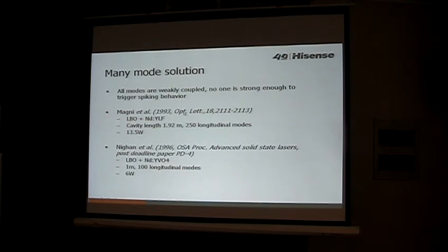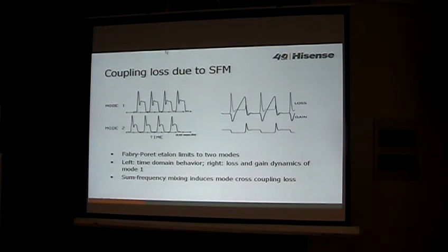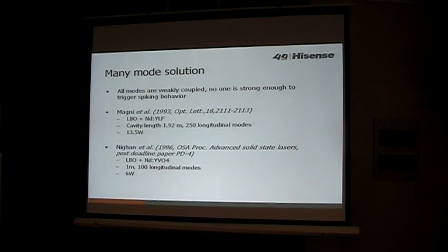For example, if we design a laser cavity with over 100 modes, all these modes will be weakly coupled through some frequency mixing. If all these modes are weakly coupled together, then no one can single out. We won't find any kind of spiking behavior, so everybody will be equal. Nobody can stand out. With this many-mode solution, we can definitely get a very stable operation.